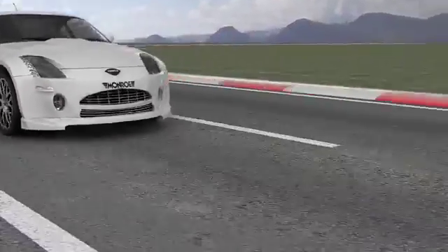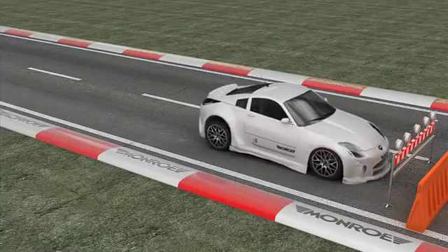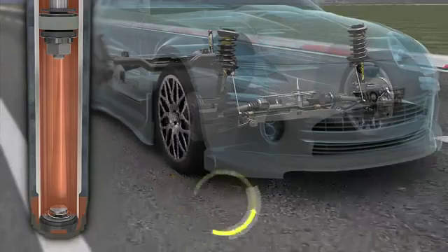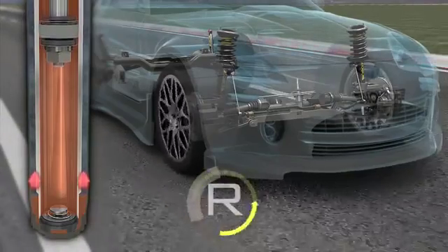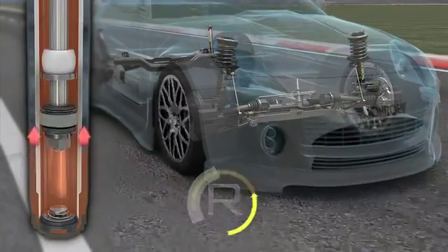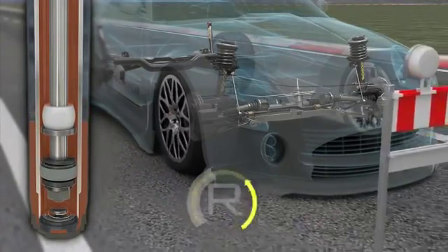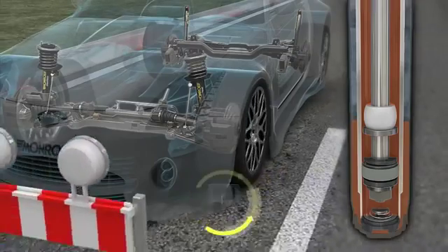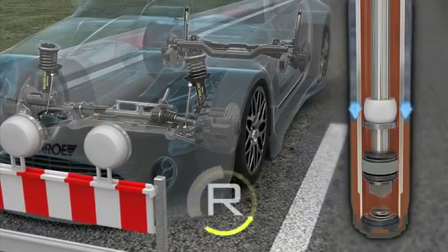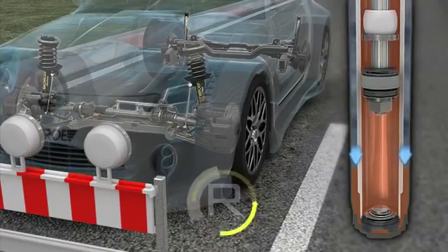Filling with gas creates a reinforcing effect in the shock absorber, which enhances the spring rate of the vehicle. When the shock absorber is compressed, the rising oil from the working chamber enters into the reserve chamber, compressing the gas housed in it. When the shock absorber begins to rebound, the force of the expanding gas helps the shock absorber to rebound more quickly.